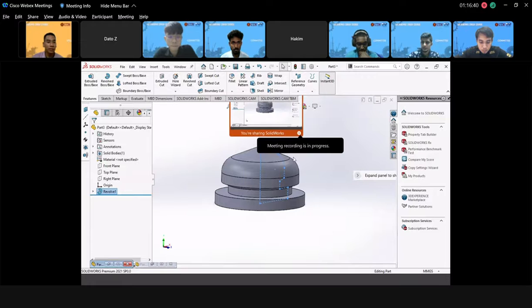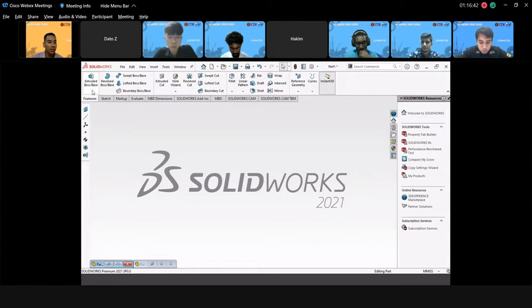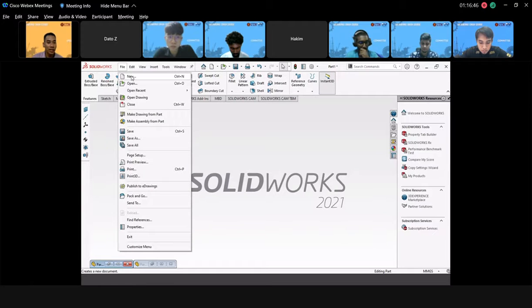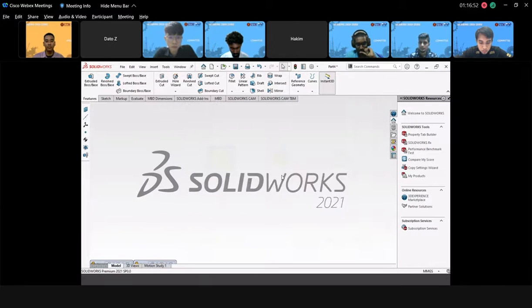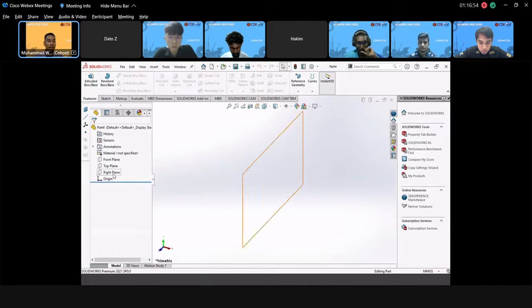Let's say go to file, new part again, and let's say I choose the front plane.